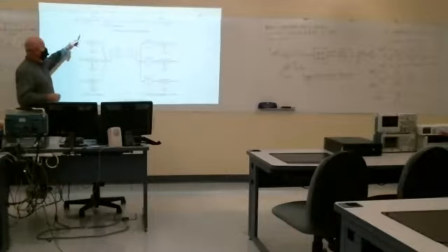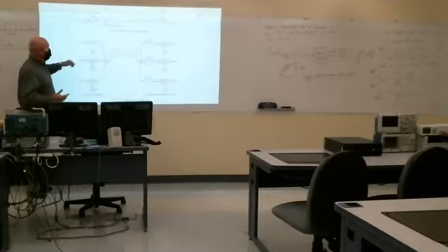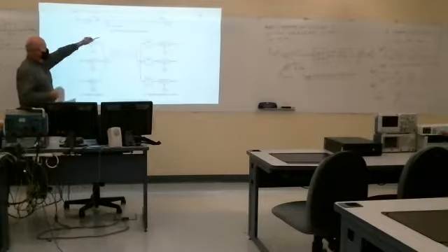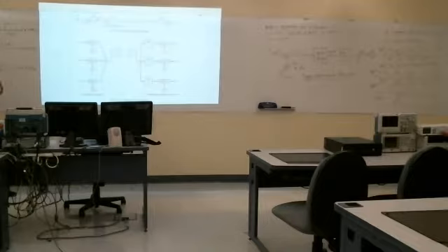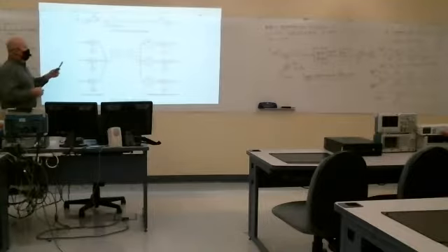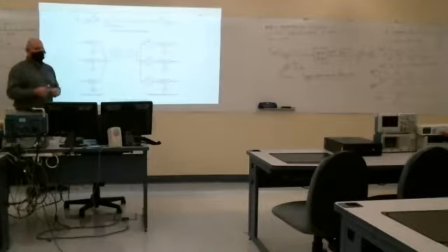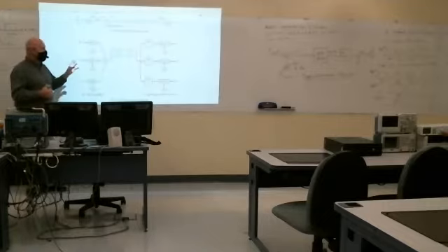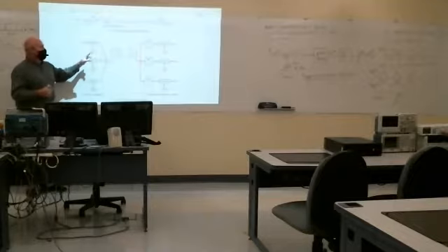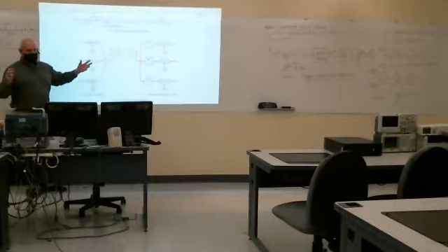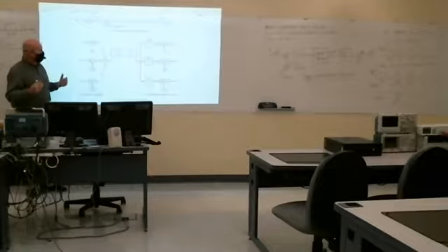Here they're showing using a wireless system and using a spectrum between 1 gigahertz and 1.01 gigahertz or 10 megahertz bandwidth to carry a number of different voice channels simultaneously. So this might be something like a microwave link that would carry, I think it's about 2,500 different voice signals here in this 10 megahertz band.